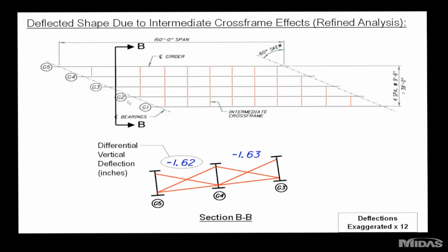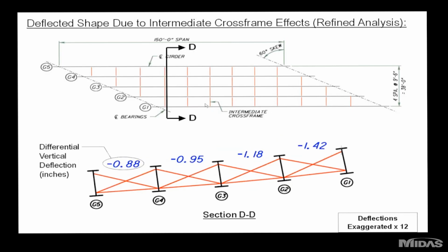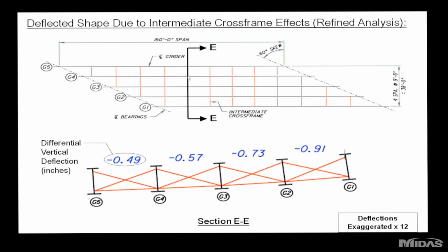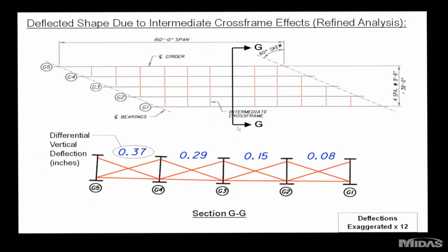We get similar behavior here. We've got girder 3 at its bearing point, so everything's falling away from 3. Again here, girder 2 and girder 1. So we're leaning away from that support. As we cross out into the span, the structure starts to flatten out. We get near mid-span, it's relatively flat, starting to reverse itself.